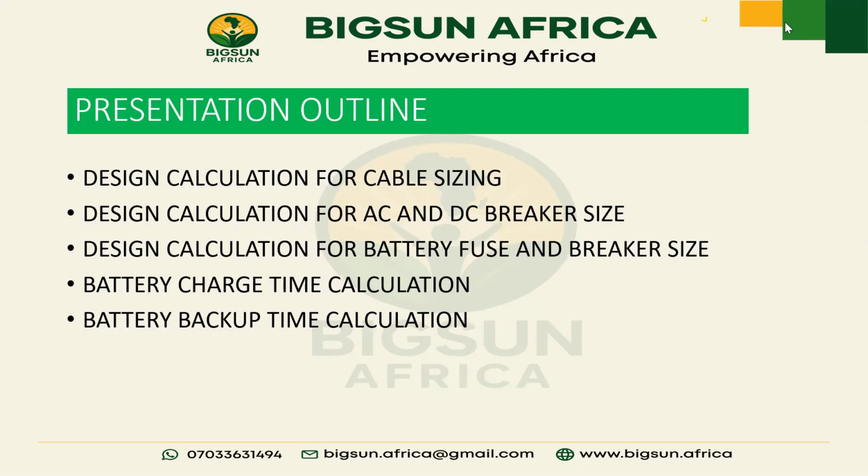Then the inverters, they have ranges of inverters starting from 900 VA to 10 kVA, and they also have what are they calling it? Hybrid and transformer base. So, hybrid is the one that has a charge controller, while transformer base doesn't have a charge controller, and it's strong. Like the lifespan is stronger than the hybrid in some cases.